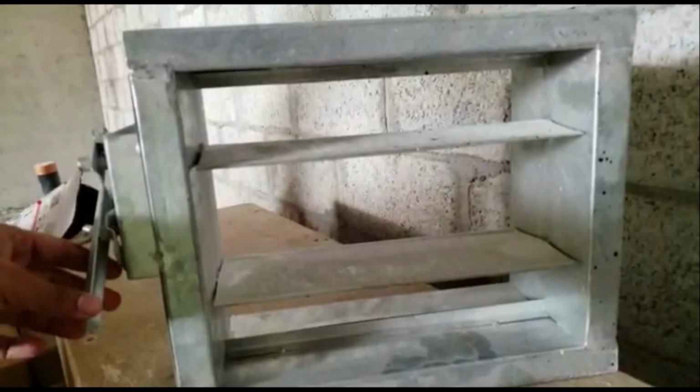I'm telling this for a basic understanding because we will be discussing the frames and the blades and the project specification afterwards. So just understand that this part of the VCD is called a VCD frame, and these are the VCD blades, like 2 blades are there, and these are in aerofoil construction. We discussed the blade constructions. This is aerofoil blade construction. 2 blades are there. This is the VCD frame, and this is the VCD handle or the quadrant, and here you can see the lock nut which will lock the handle at a particular position.